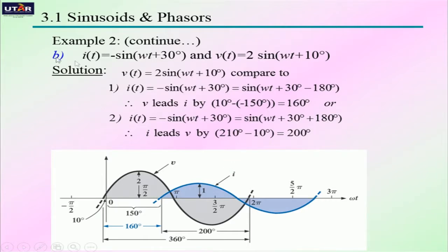Same goes for question B. In question B, we can see that voltage leads current by 160 degrees. Of course, we have to change both current and voltage to the same trigonometric function before we compare their phase difference.